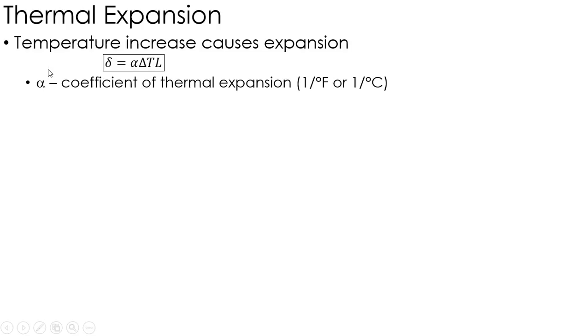You can look it up in the back of the book in the tables. Once you know that and you know the change in temperature and the original length, I can find the deformation, the elongation of that rod. So really that's pretty straightforward to figure that out.